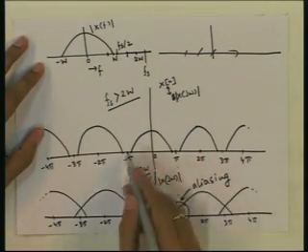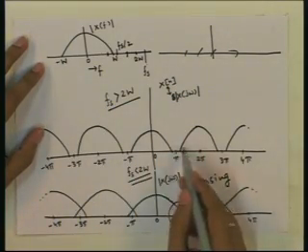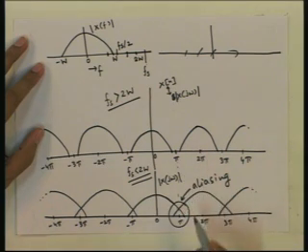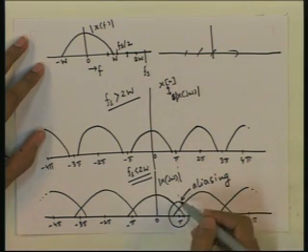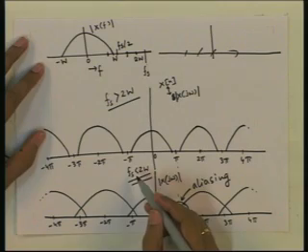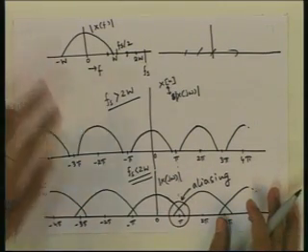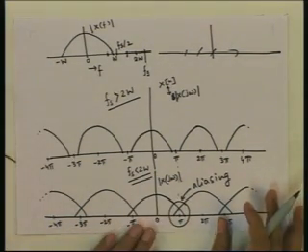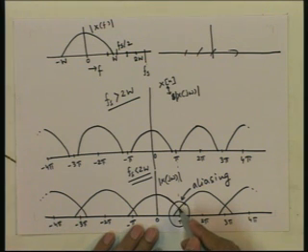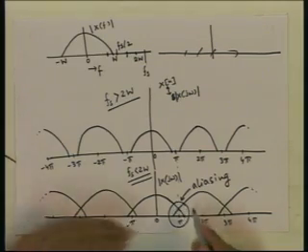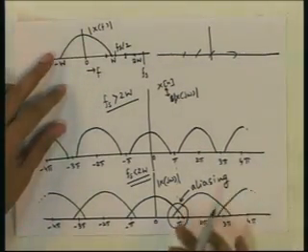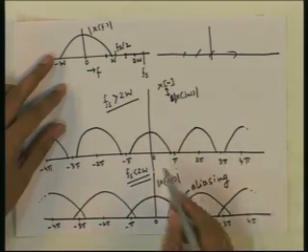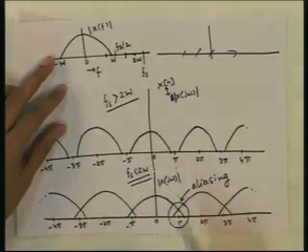Now, when we do this, there may be mixing of different components and that is called aliasing, and that mixing will happen if the sampling frequency is less than the Nyquist rate. And so that is not desired, because in that case we may not be able to recover what these values are from the mixture of these two copies. On the other hand, if there is no mixing, then we can recover this original spectrum from here, and we saw how to do it.